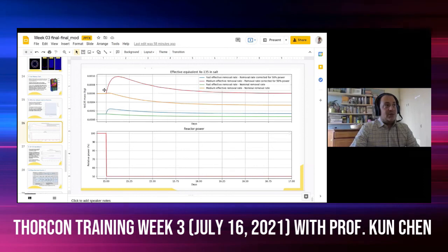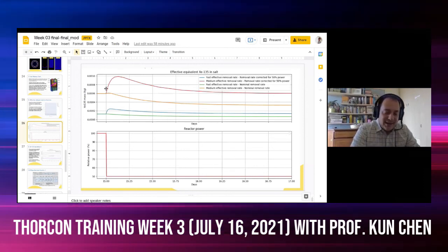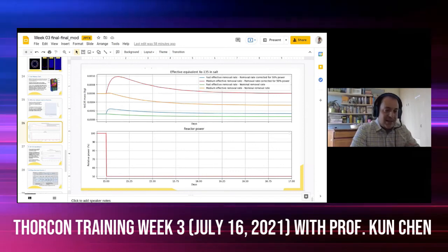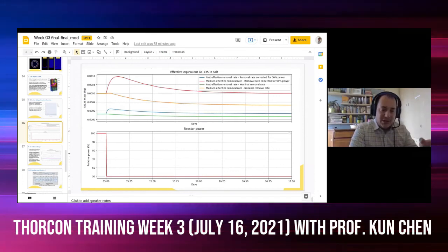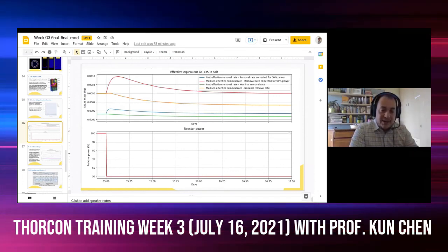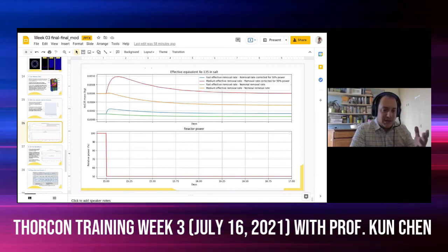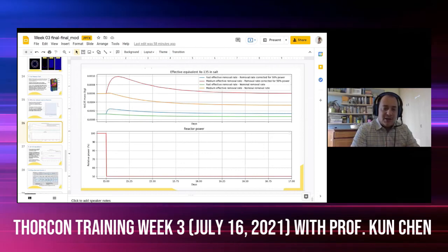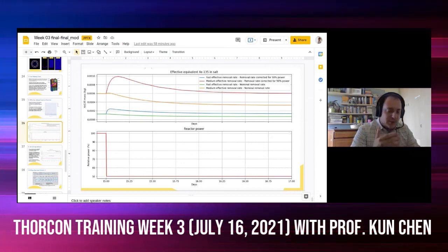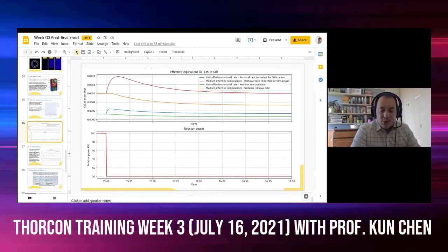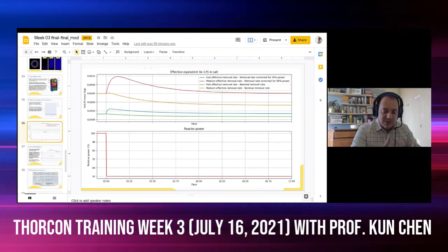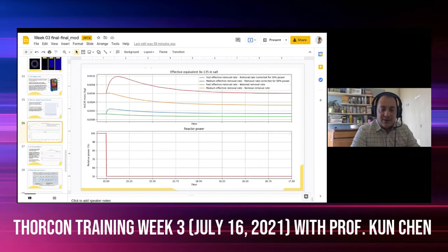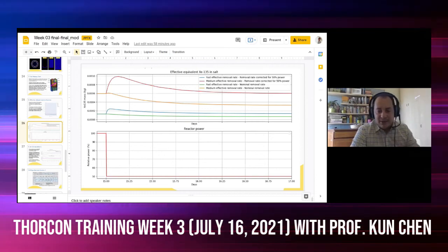It is also to say that the removal rate is not a removal rate in the sense that I'm removing a given amount of xenon per time interval. I'm removing a fraction of xenon. So if I double the xenon and I keep constant the removal through the same exposure of salt to the gas, or the same rate of salt through the gas-salt interface, I will be doubling my removal rate.